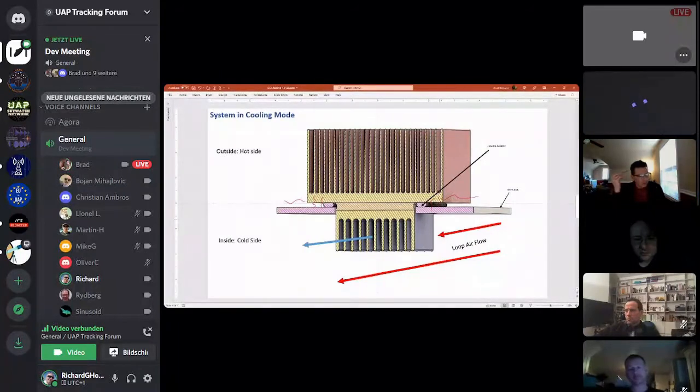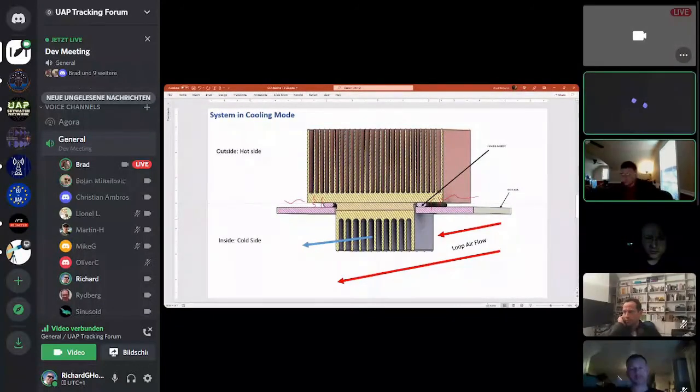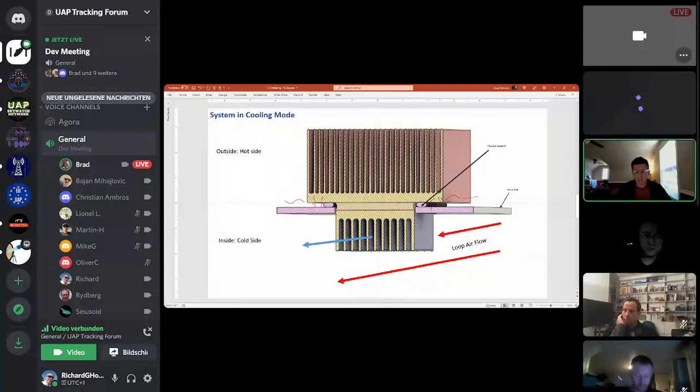What about designing a tiny little frame that's just a little bit bigger than the peltiers themselves, to set the peltiers inside, printed from plastic, and providing a kind of standoff so that the heat sinks are separated from the peltier with these copper plates. One of the problems with the copper plates is it'd be great if we can get them within 1mm because they do more in terms of spacing. Yep. But every time you add an additional layer, this gets to the issue of do we use thermal grease or thermal glue? Yep. I can tell you thermal glue is kind of a pain in the ass.